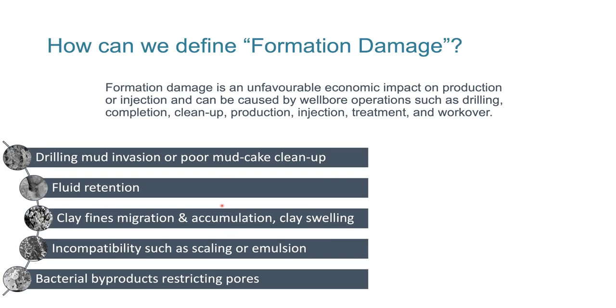Incompatibility, this is something again we see all the time. So scaling from injection water, for example, or scaling from production differential pressure, emulsions from completion or drilling fluids interacting with reservoir fluids. This can be fluid or rock fluid. These are all sources of incompatibility.